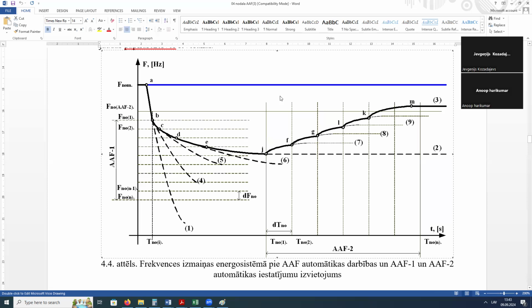Automatic will do this without any stress, just using the algorithm. In this case, I think that the second under frequency automation must be in every power system. But in Western countries there is only the first type of under frequency automation, and as a result, we will see different blackouts that could not have happened if there were a second type of under frequency automation.